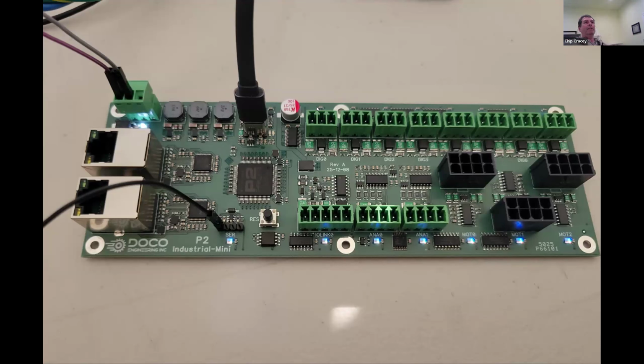the next LED state. Oh, and the way this thing works in hardware is down here is a 74HCT74, because it's powered at 5 volts but fed by 3.3 volt logic. And what that thing does on the upstroke of the clock, we're sending data around the I/O expansion chain, right? Every clock rise, it's a new bit out and we get another bit in.